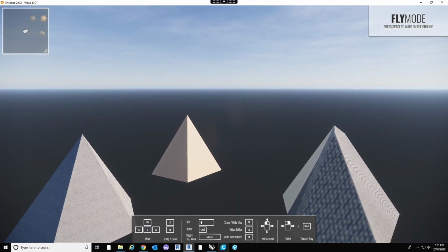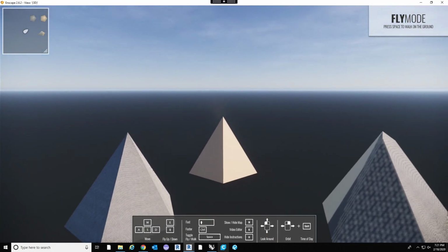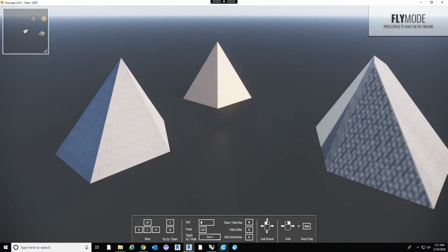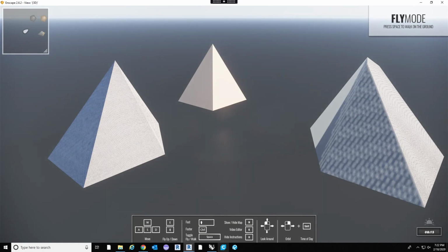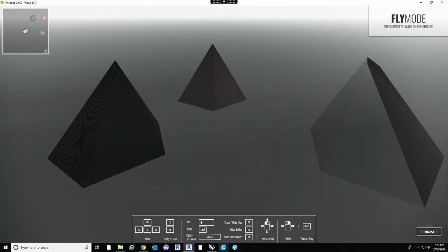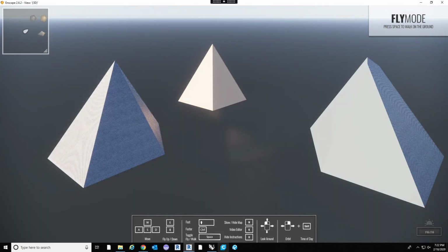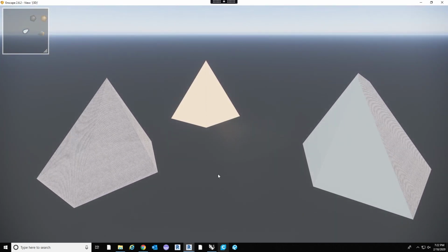Sorry. So Enscape is a realistic rendering software. So you have control of the sun and of lighting. And if you want to change the time of day, what you do is you hold down Shift and then hold down the right mouse button and pan either to the left or the right, and in the bottom right corner, you can see the time of day and where the sun is setting or rising. Alright, those are kind of the basics.